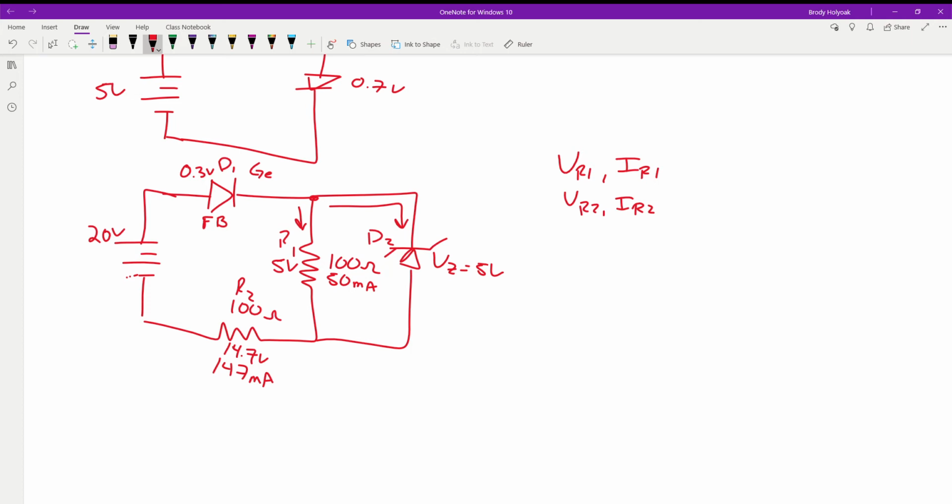Okay. Pretty easy. You'll see circuits like this. Once we start getting into AC, diodes are going to become a lot more common because we use them to control it. Because there's times we don't want negative pulses to come through. We want it to turn on and then turn off. Turn on and turn off. We don't want it to turn on, reverse directions, and then turn off.